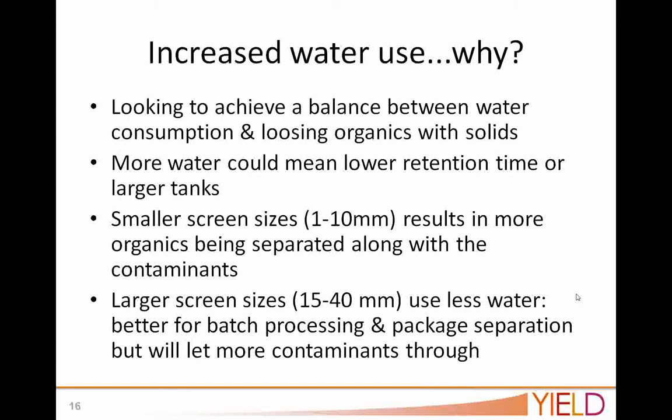So one of the main considerations is that all of this equipment has a total solids working range, and of course you have feedstocks that have a range of total solids. So looking at what your plant is going to process, what feedstock contracts you have, what this material is, and trying to match the right technologies to the feedstock, to minimize things like water use and parasitic electricity consumption. Water is the big one because it costs you to purchase it, it costs you to pump it, and it costs you to dispose of it.